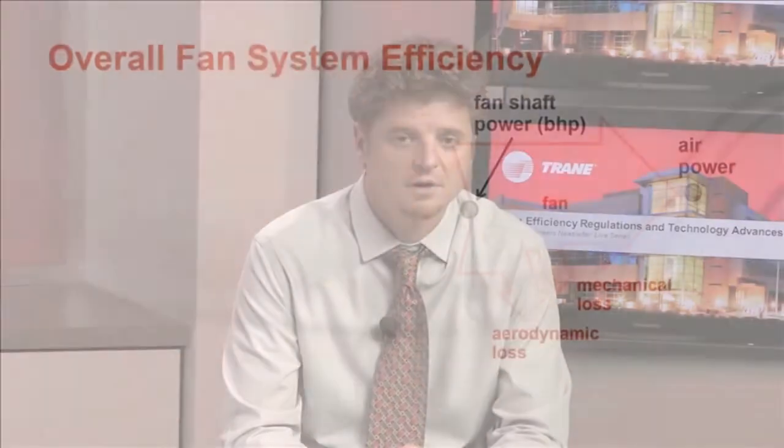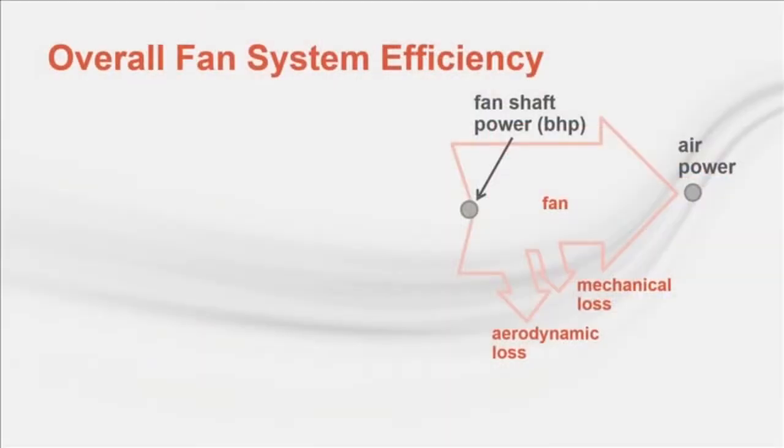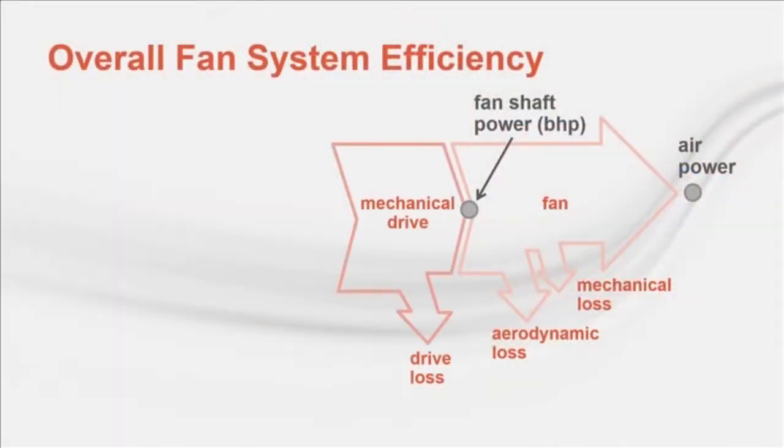When analyzing the efficiency of a fan system, one must consider all inefficiencies involved. First, there's the efficiency of the fan impeller itself. Motorized impellers utilize a high efficiency backward inclined impeller. Thus, the aerodynamic efficiency of the impeller should be similar to a DDP fan. However, the external rotor motor can reduce the overall fan efficiency since it protrudes through the fan inlet. Next, there are losses associated with the drive kit. Of course, direct drive fans do not have any losses here.